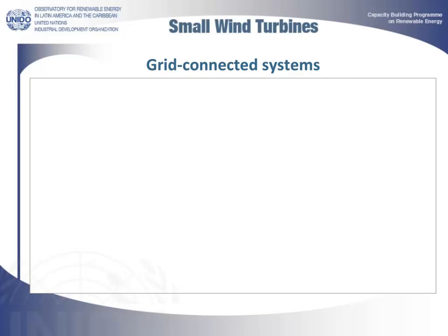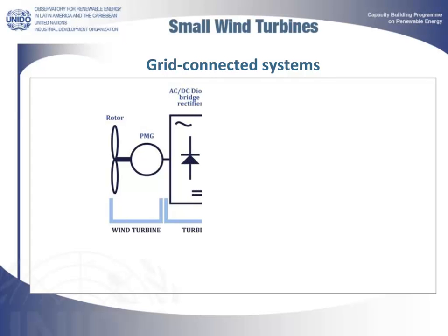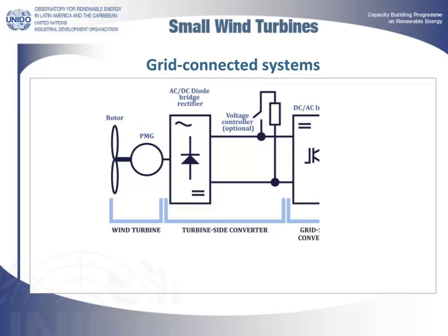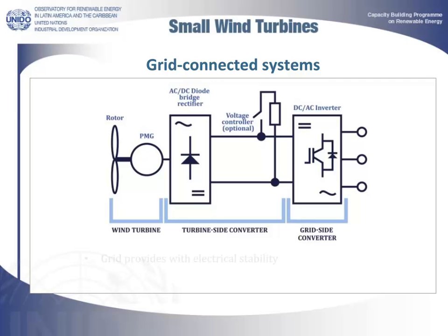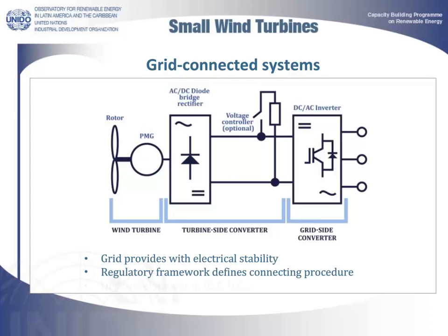The most common mini-wind grid connected configuration is shown in the figure. The components have already been described in the reference to mini-wind technology. From a technical point of view, the electrical connection of mini-wind does not represent any greater complication than the adjustment of the parameters of the inverter with those of the grid. The situation from a regulatory and an administrative point of view is very different, because it depends largely on the site where the installation is to be made.